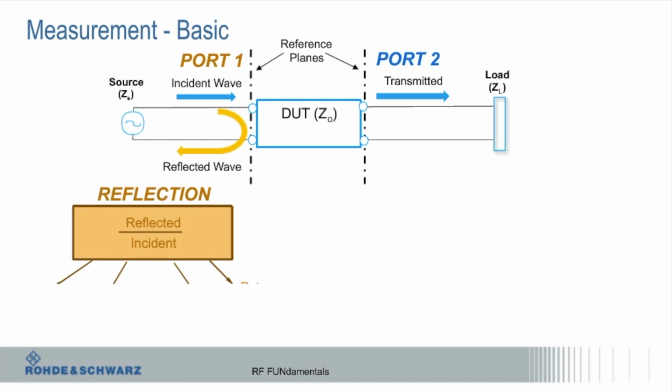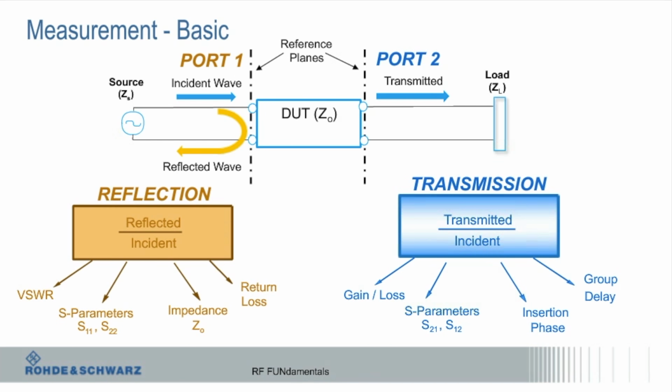Port 1 and port 2. So this is all VNA stuff. Fundamentally, a VNA measures S parameters, so don't let anybody tell you otherwise. All the other stuff, it basically takes those measurements and manipulates them mathematically to get other stuff. After I do it, I get S11, S22, S21, S12. S11 is basically the reflected at port 1. S22 is the reflected at port 2. So obviously you get a mismatch anywhere. S21, if I'm going this way forward, might be the gain or loss of my device.